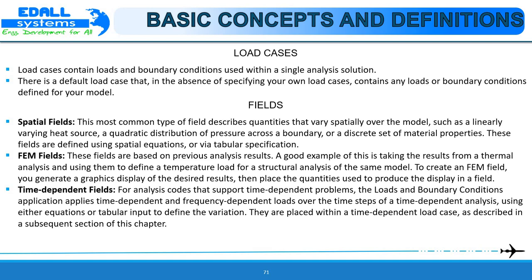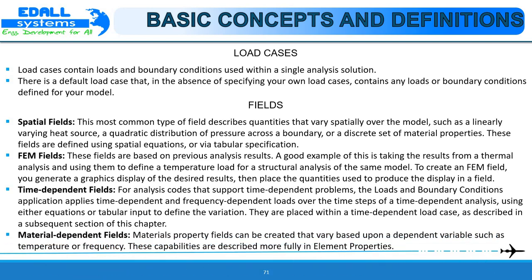Next one is the time-dependent field. For analysis codes that support time-dependent problems, the loads and boundary conditions application applies time-dependent and frequency-dependent loads over the time steps of a time-dependent analysis, using either an equation or a tabular input to define the variation. The last one is the material-dependent field, where material property fields can be created that vary based upon a dependent variable such as temperature and frequency. These capabilities are described more fully in element properties.